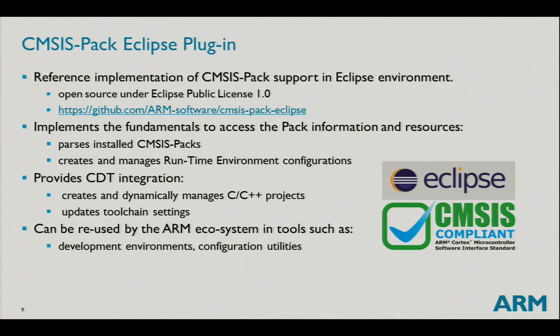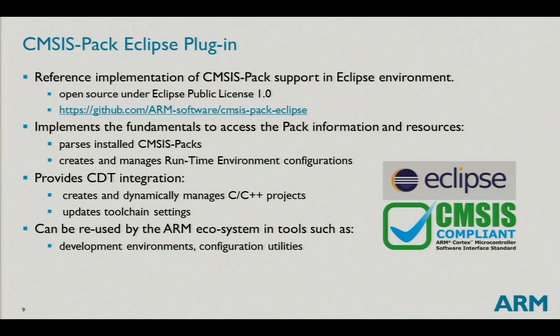Inside, it implements the basics, so how to access the pack information, how to create a so-called runtime model to manage this information, and it has the CDT integration, so it really allows you to create the project and build it. The plugin is primarily intended for the tool developer, so it's not an end-user plugin. You have to customize it. You need to provide the toolchain support, so binding, and most probably the connection to the debugger, because the plugin itself doesn't provide the debugging support.